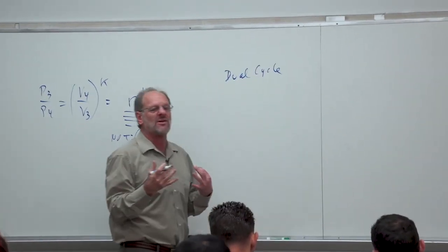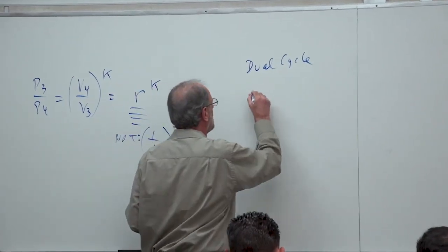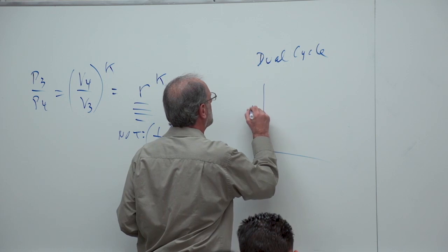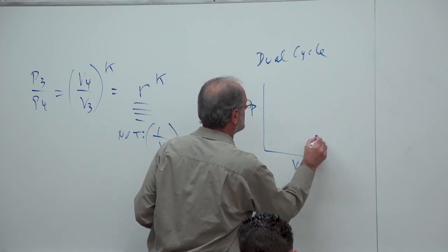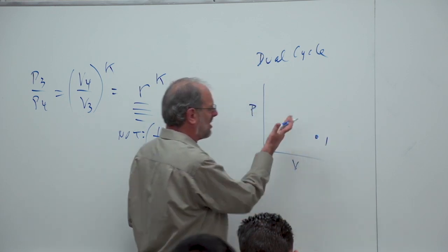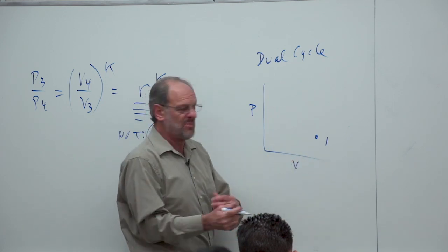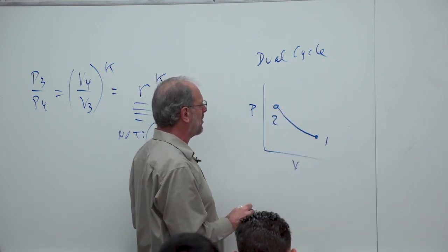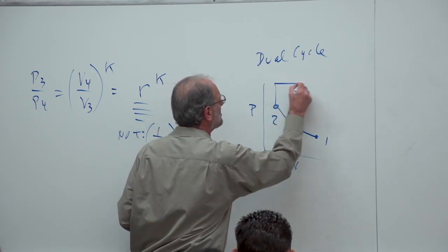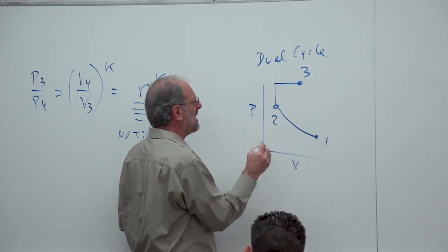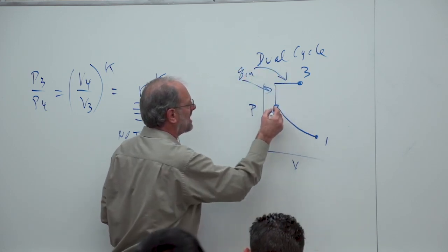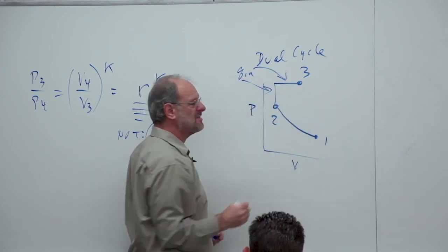This is very briefly mentioned in your textbook, and as long as I'm just covering random topics here, I would note that for the dual cycle, we'd still start at the maximum volume at bottom center. We'd still provide isentropic compression up to point 2, but now we'd have heat input in 2 steps, partially at constant volume and partially at constant pressure.